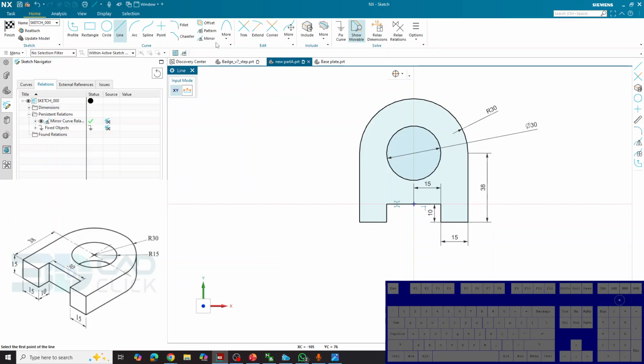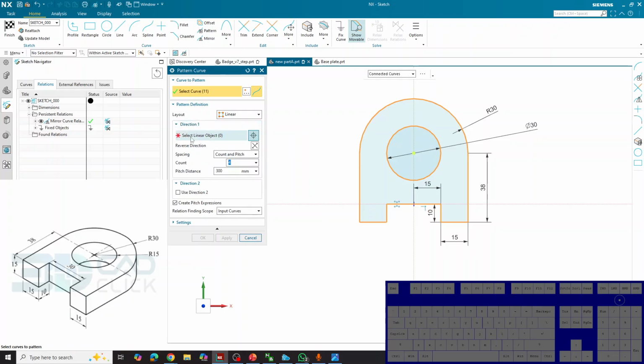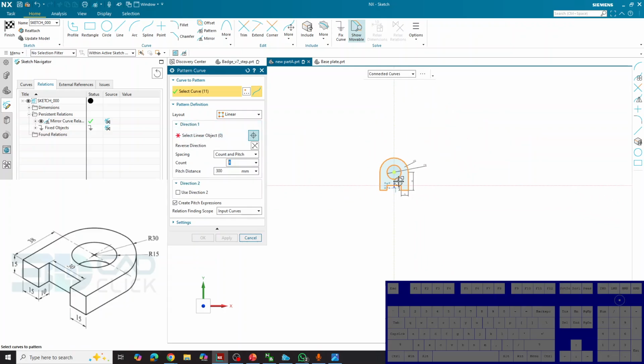So let's start by trying to use the pattern tool. The pattern tool is over here, and it will ask us to click on the lines that you want to basically duplicate as a pattern, okay? We will select this line here, and we will select the rest of them as well. We'll select this circle over here also. We want the pattern to be, let's do circular. Let's do linear. Okay? Pattern direction. Which way do you want your pattern to go? Do you want it to go right, up, left, or down? Okay? I will select the pattern that goes towards the left, okay?